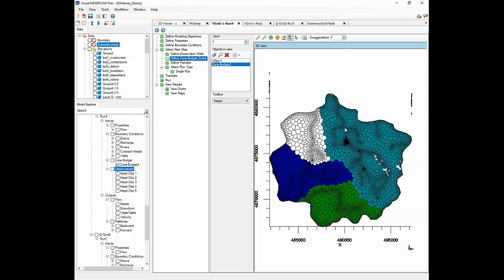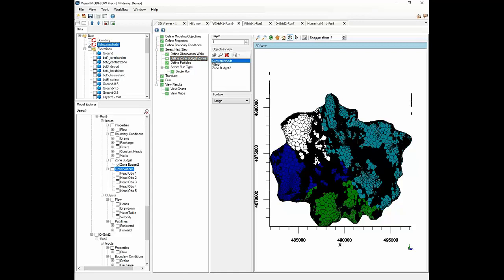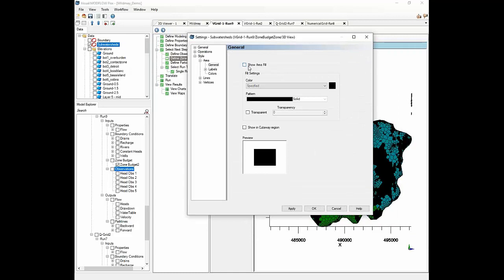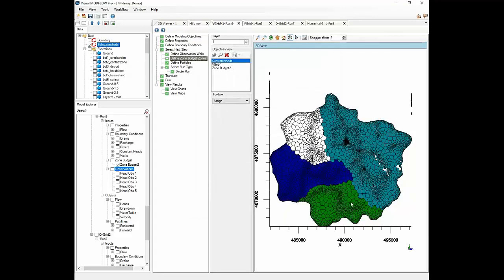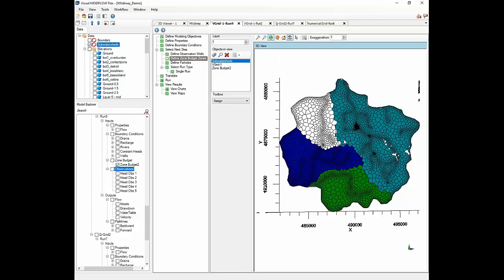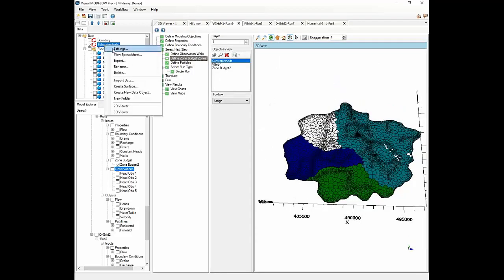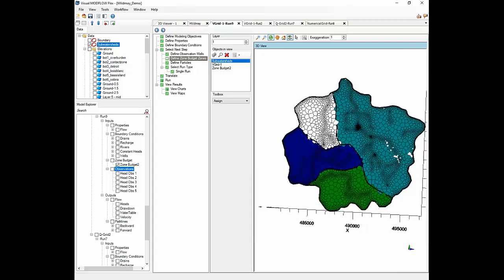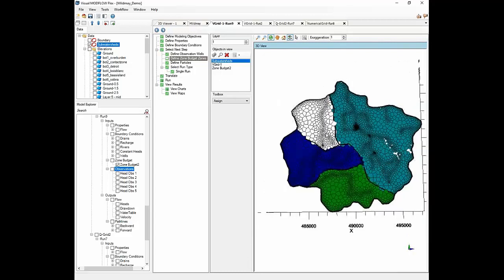So you can see that we've defined the zones pretty quickly using the attributes here, and I'll turn on the sub-watersheds. Let me just change the styles for that. And actually I think it's sitting under the model. Actually it's the thickness, we'll be able to see it a little better. There we go. The zones conform fairly closely to what you've defined. And if you actually use those sub-watersheds in generating your grid, then it would actually conform exactly.